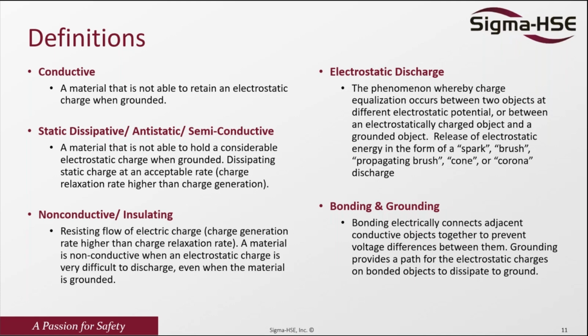So if it is not grounded, and we'll go into the grounding and bonding very soon, if it's not connected to the earth, that means the charge accumulation will still stay there. But as soon as you connect it to the earth or grounding, then the electric potential will actually be zero. It will dissipate all the charges. That is a conductive material.